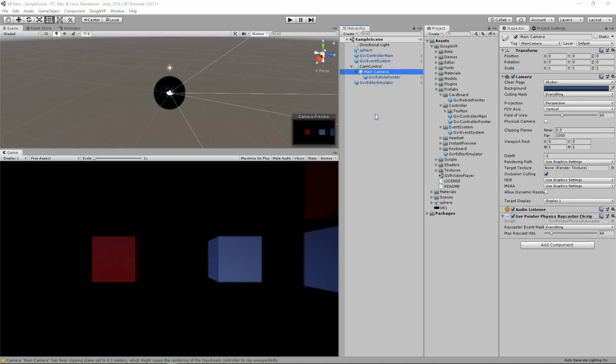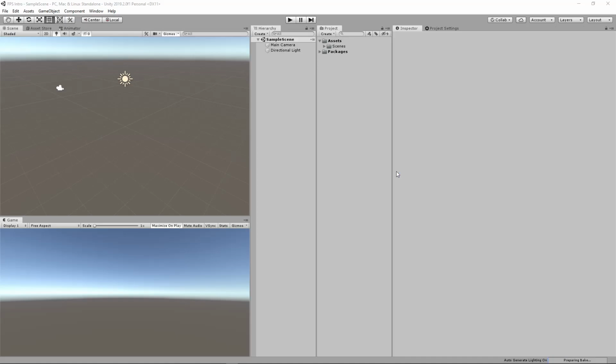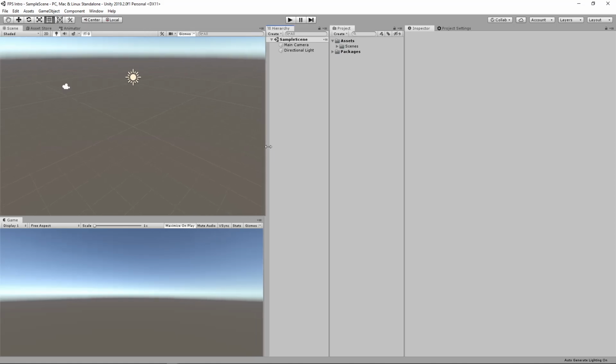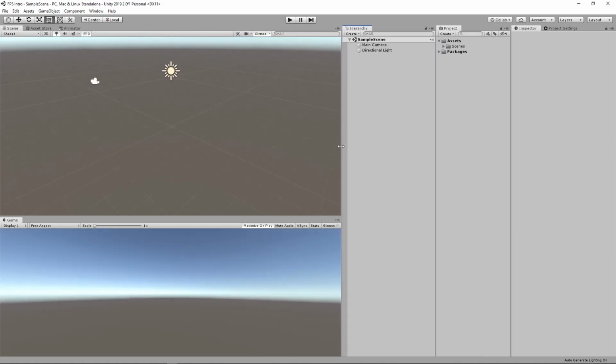So well, we're trying to bring objects out of Blender and into Unity, and so a blend file, for example, won't open in Unity. A blend file is only compatible with Blender. There are lots of different types of file that we can open here in Unity, but the one that's most applicable to us is an FBX. But there are some consequences to setting up an FBX file, which we'll look at now.